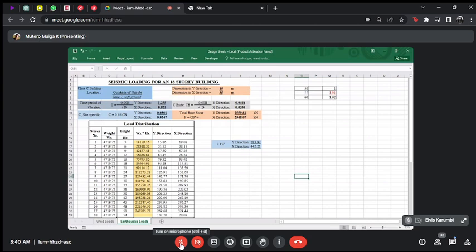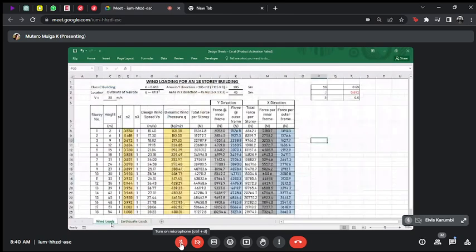And my desire was that by the time we get to that point where we say what size of shear wall and where do we put it, if you could have the models ready and maybe even loaded with these lateral loads, so that when we discuss in class, you go and actually put those shear walls and run the analysis and see the implication of having a shear wall at this point or the other one, because there are serious implications of where you place your shear walls and the size of the shear wall as well.